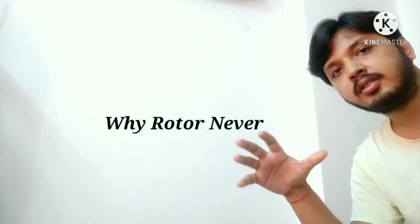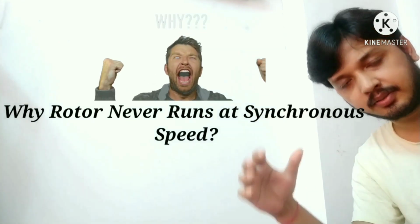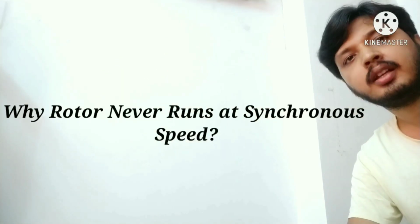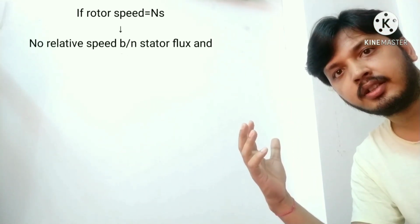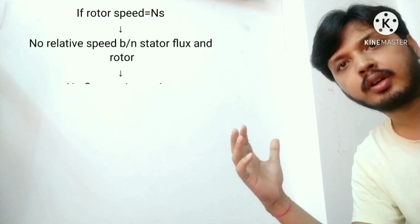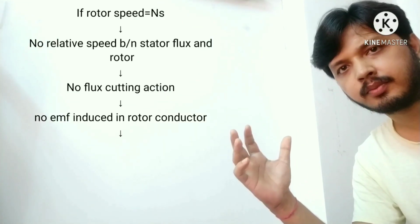Now the question is, why does the rotor never run at synchronous speed? If the speed of the rotor equals synchronous speed, no relative motion occurs between the rotating magnetic field of the stator and the conductor of the rotor.